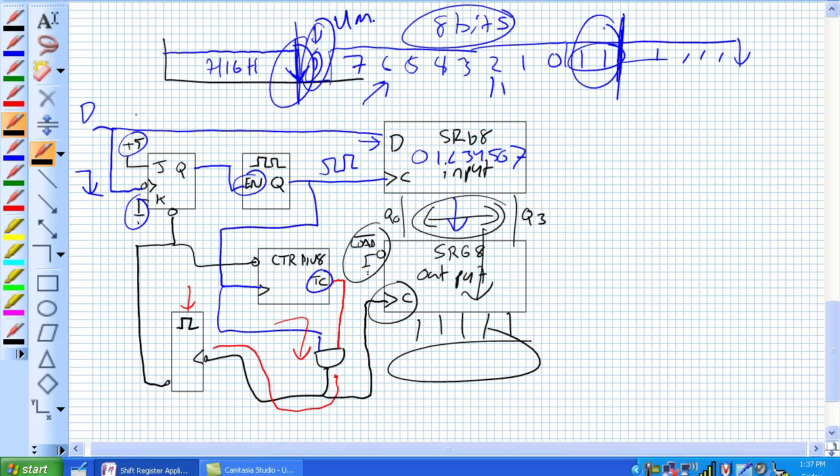And then the data is high, high, high, all of a sudden bang, it goes down again. The whole process starts over again, where you're feeding into this input register and then counting up. Once it hits 8, it goes ahead, clears everything. Before it clears everything, it loads it into the output available for your viewing pleasure. Rewind, restart, rewind, restart. Okay, let's go on to, oh, there's a keyboard encoder application in your book too.